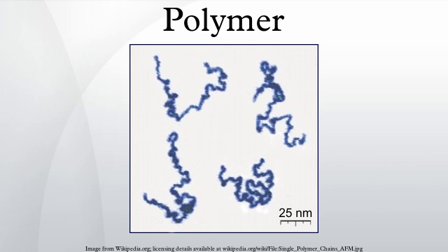Phase behavior: melting point: the term melting point, when applied to polymers, suggests not a solid or liquid phase transition but a transition from a crystalline or semicrystalline phase to a solid amorphous phase. Though abbreviated as simply Tm, the property in question is more properly called the crystalline melting temperature. Among synthetic polymers, crystalline melting is only discussed with regards to thermoplastics, as thermosetting polymers will decompose at high temperatures rather than melt.